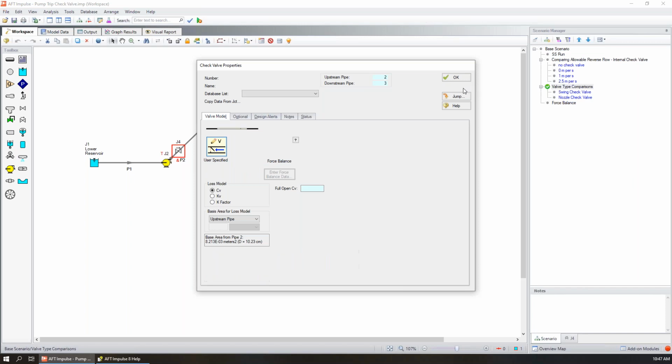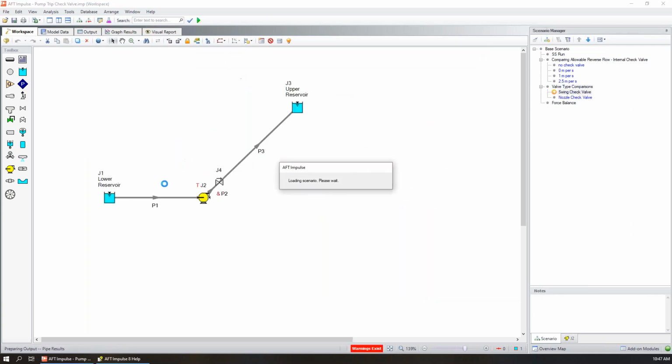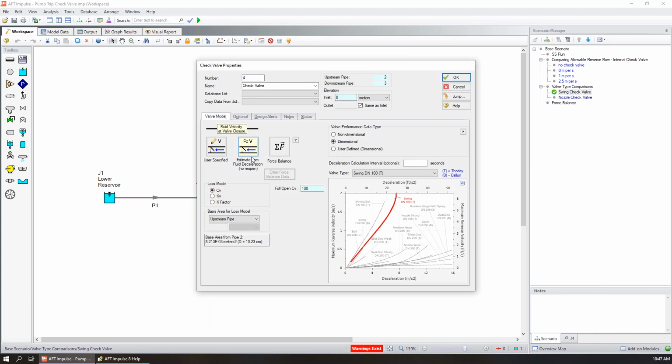So just like what we see in the combined check valve and pump, where it's that forward velocity to close, delta head to reopen. Easy enough. Where we get more complex and a bit more interesting is this fluid deceleration. Again, it won't reopen, so if your pump restarts or if you have chattering check valve concerns, this would not be the best option in those cases.